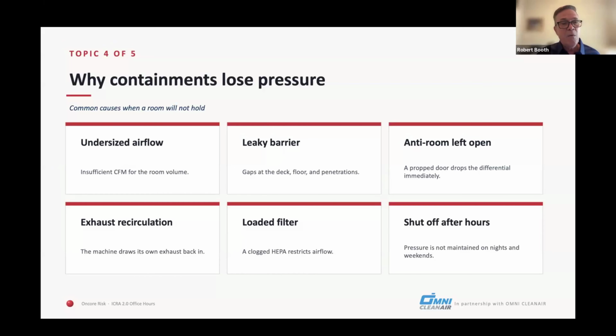But basically, we have contractors that use some of that cooling from the supply from the existing HVAC system. Yeah. And that's prohibited in the guidelines. So we basically put in there you can't use anything for recirculation in an active air handling unit. But also the reason we want you to close the supply and return is so that you're not affecting that space with other systems that you're going to have to overcome. That's a big challenge. And I hear that every week.